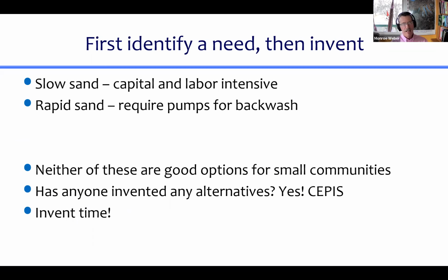So I've given you some background on what's going on inside filters, the concept of porosity, minimum fluidization velocity, head loss through clean sand. And now we have this problem that we could use slow sand filters, but I previously made the case that slow sand filters are interesting, but they're big because they're slow. And because they're big, they're capital intensive. And because they don't have any way of automating or mechanizing the cleaning process, it means that they're going to be cleaned by hand.